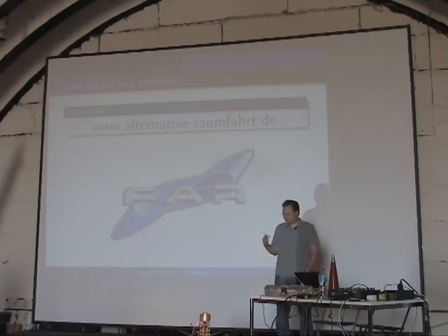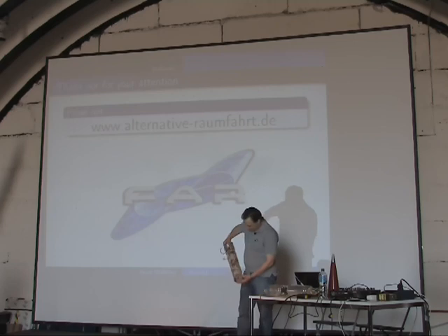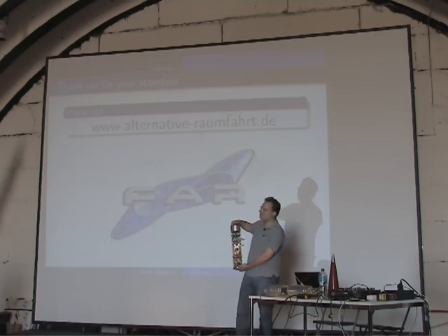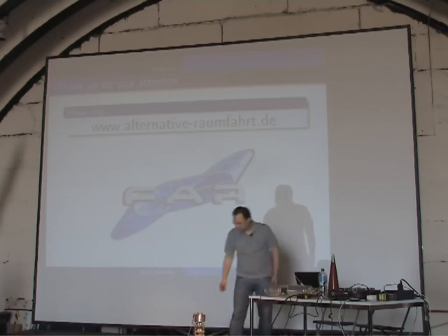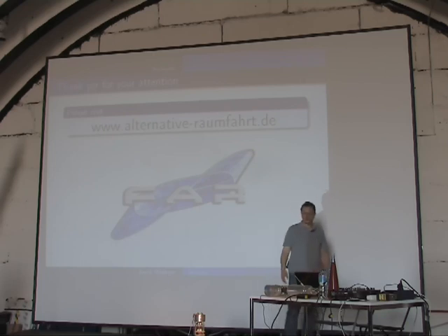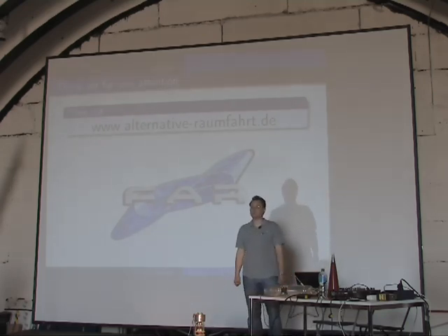Okay, the most power consuming subunit is the telemetry, especially the radio beacon here. This consumes a lot of power. How much is it? So at 12 volts, a little more than 1 watt. It's very powerful for its size. But in total, we can run this avionic for hours on a fresh battery pack. Yeah, so 12 hours or so or more.